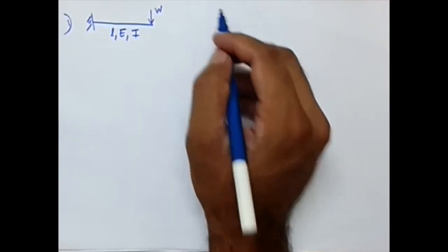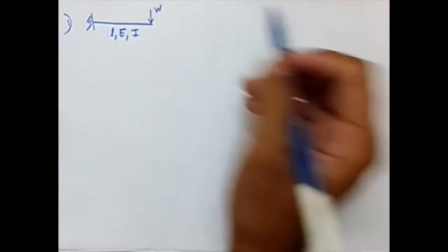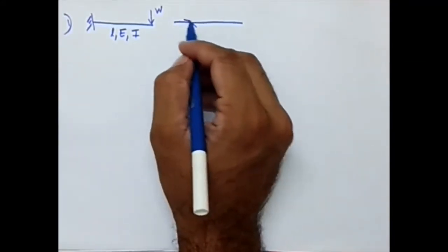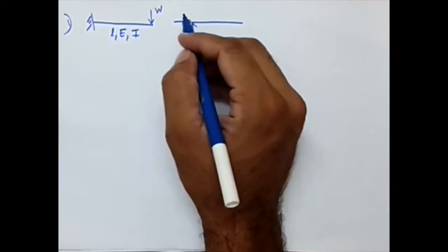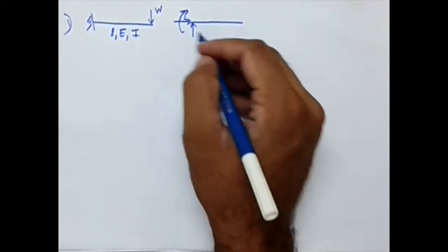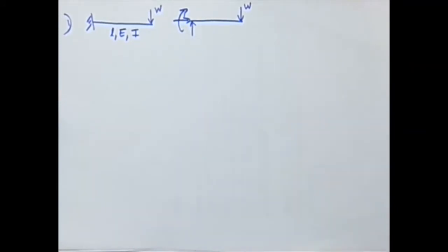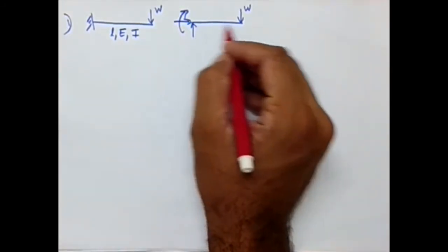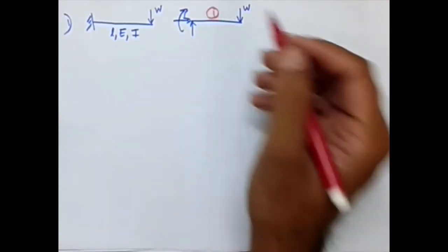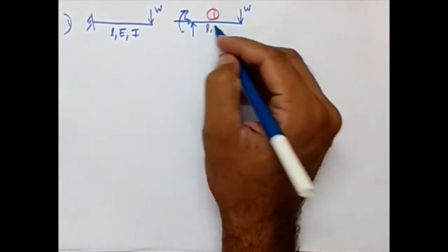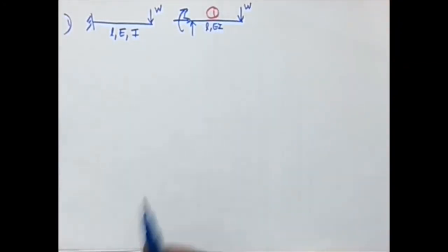What we used to do is divide it into segments. If you represent this beam with reactions, at the fixed end we are going to have vertical, horizontal, and maybe a moment reaction. Three reactions may be there, and here we have the external load as given in the problem. The beams are divided into segments depending upon the location of point loads. Here this is one point load location, this is another, so you just need one segment, and that segment has the properties L and EI.